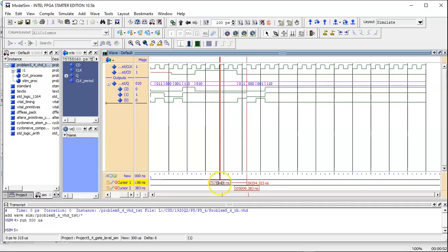And then if you've got the system with this CD high, nothing happens, because the digital system, whatever it is, synchronous or asynchronous, is blocked, is in the reset state. Then when you are deactivating the clear direct signal here, now is when the system starts changing states.